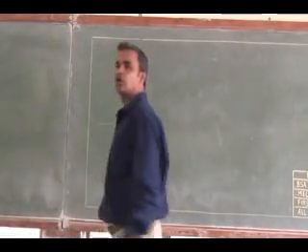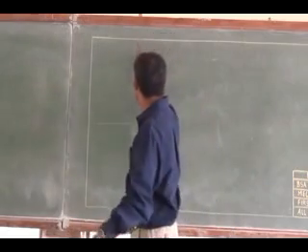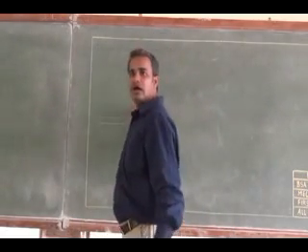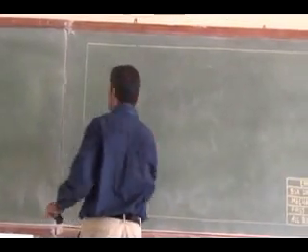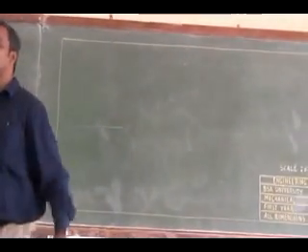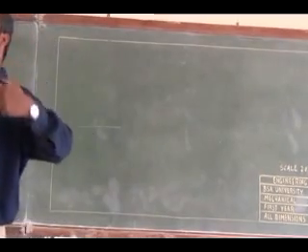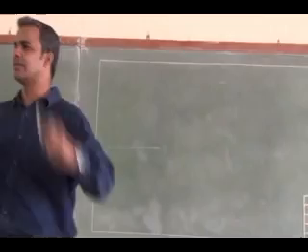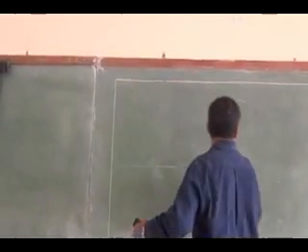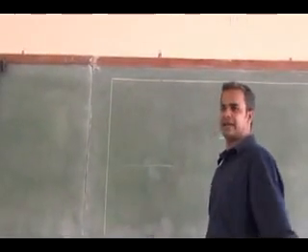So take a 2H pencil and draw a horizontal line parallel to the reference layout line. So this is the horizontal line, the 2H line. To this horizontal line, I have to construct a square. You can construct a perfect square like this.